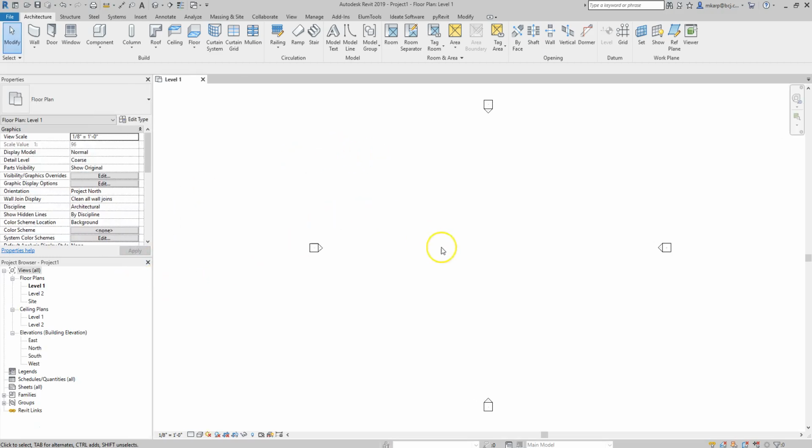Alright, so just some very basic stuff about REVIT, just to go over what we're looking at on the general screen here. So over here, this is your project browser. This is how you get around in a REVIT model. You can see all your views up here, legends, schedules, sheets. We don't have any because you can't expand any of these. Families and groups. So families are some of the building blocks we use to make these models. You can see when I came in, it drops me on level 1 right here, and that's why that's in bold, because that's the active view.